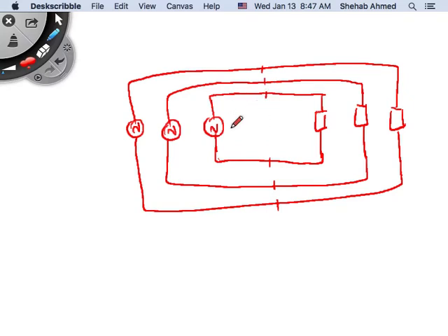These cables carried a certain value of current, right? The current going out here is what's going into this load. Assuming the loads are equal, the currents in all 3 conductors are the same. So this is what you would have to do if you were going to feed the system using single phase. If I was to transmit power on 3-phase, how would things change? So let's look at this.